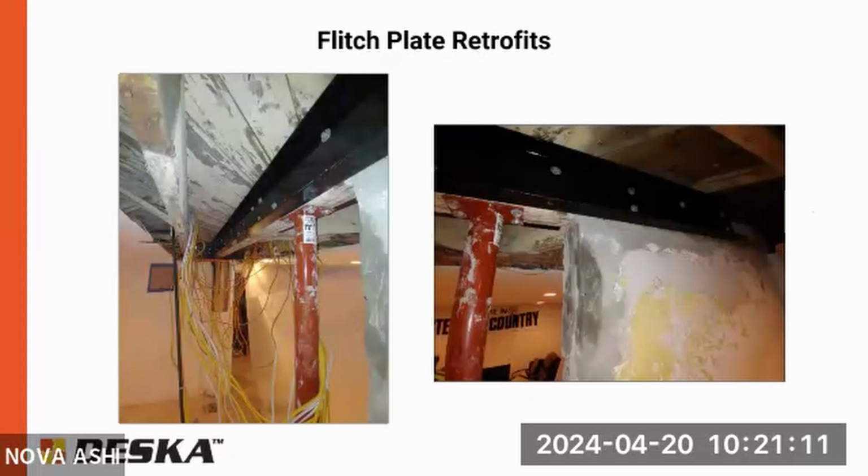This is an example of something similar to sistering, but we call it flitch plating. If you have, typically not joists, but beams, timber beams, and they're sagging or there's some issue with them, or you're adding a load to them, you can sandwich them with steel plates, or in this case, a steel channel. You through bolt them and it can add a lot of capacity to the beam.